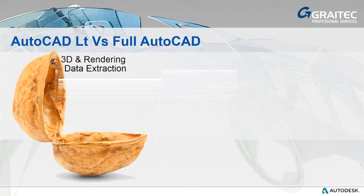Data extraction to tables, both in your drawing and exportable. With Full AutoCAD, you can do data extraction of information on blocks and attributes, and either display them on your drawing or export them out into a format that you could look at in a spreadsheet such as Excel.